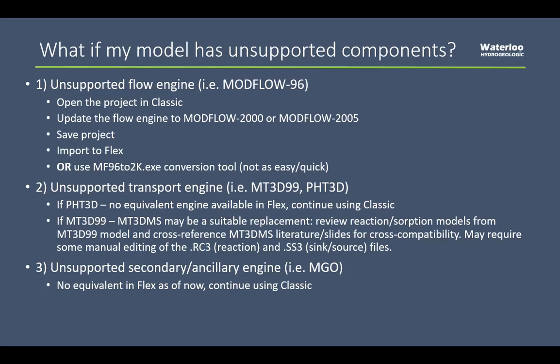Now, if the transport model is based on MT3D99, then MT3DMS or another contaminant transport engine might be a suitable replacement. So in that case, you'll want to review the original user documentation for the various contaminant transport engines and just see if there's any compatibility basically with any of the other supported flow or transport engines, primarily MT3DMS.